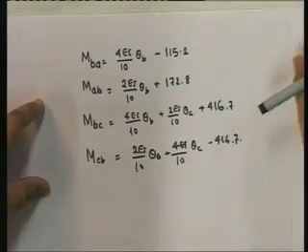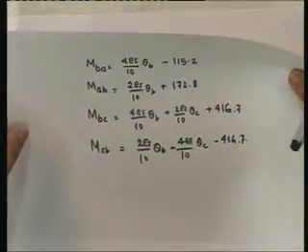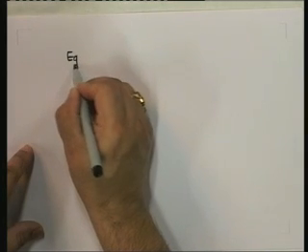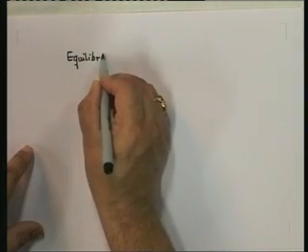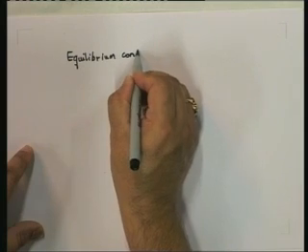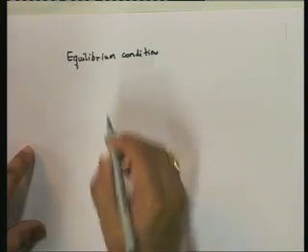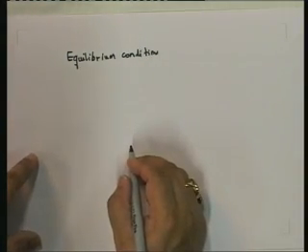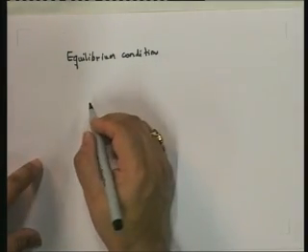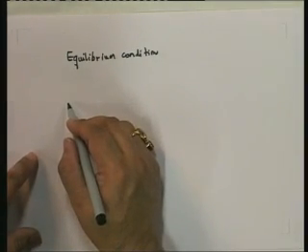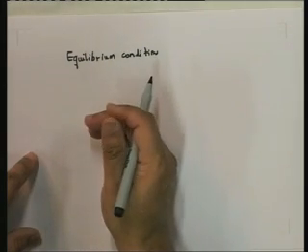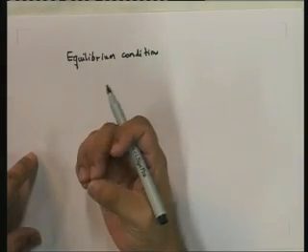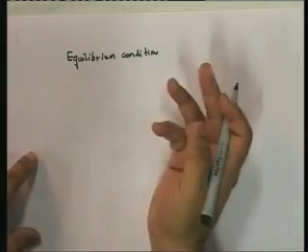Now what do I have to do? I actually have to write down equilibrium equations, which two equilibrium equations, so that I can solve for theta B and theta C. Let's see what those equilibrium equations are. So let us look at the equilibrium conditions here. At joint A, you do not have an equilibrium. The equilibrium says that MAB is equal to the moment at A. That does not give you anything.